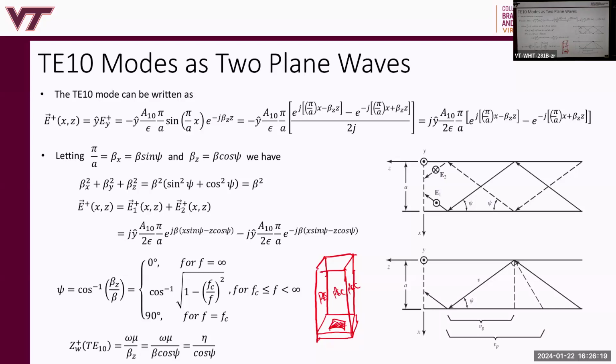By image theory, any current that's induced on this patch, say that's current J, is going to get imaged across these metallic walls like that, and in this direction it would also be imaged in this way. So the normal component doesn't flip. And by doing that, what you get is an infinite array.